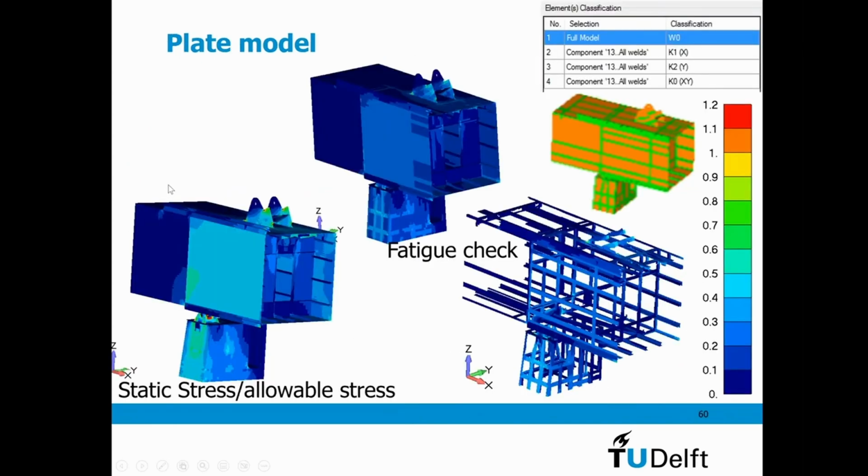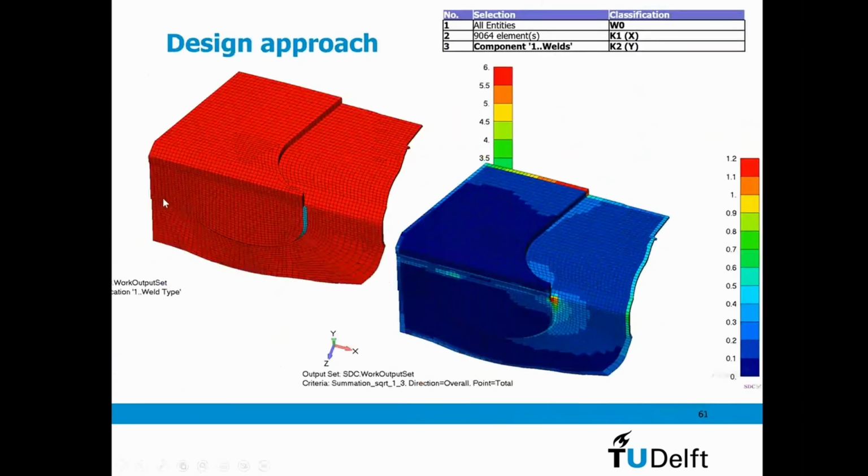Again, if we have a plate model, we have all these welds and the different classifications, and then you get results like this. For volumes, that is a bit of a problem. Besides that, nobody wants to calculate with volumes because your models get really big. It is also an issue classification-wise, because all the examples you see in the classification of the older lifting appliances standards